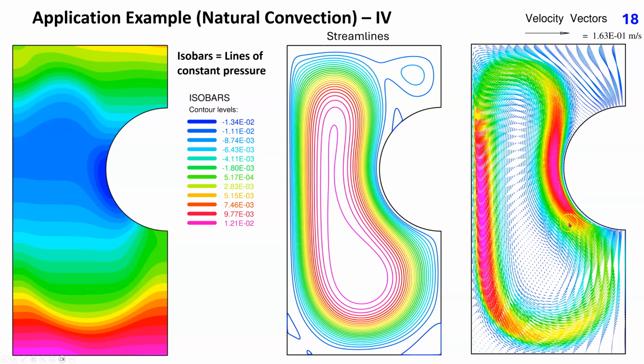Here, the heated fluid rises upward. Near the top wall, the pressure increases because the fluid stream impinges against it and needs to be redirected downward. At the bottom wall, both gravity and fluid stream impinging onto it lead to an increase of pressure. The maximum pressure is obtained directly at the bottom wall.